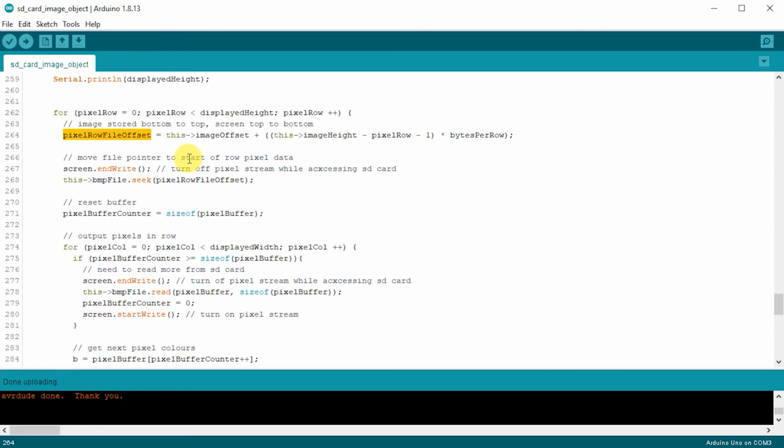Because what we're going to make use of is the idea that in these files, as we read them from our SD card, we're working with what's known as a file pointer. So far we've just simply opened a file and we've started reading, and we've got the first byte followed by the second byte and so on. But what the system is actually doing is keeping track of which byte we're about to read. So when we first open the file, it sets this file pointer to 0. So the first byte we're going to read is the very first byte in the file itself, position 0. As we then read a byte, that file pointer moves on to position 1. So the next time we read a byte, we'll read byte position 1, and so on.